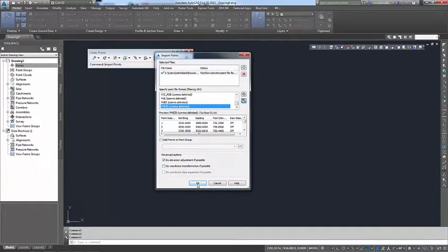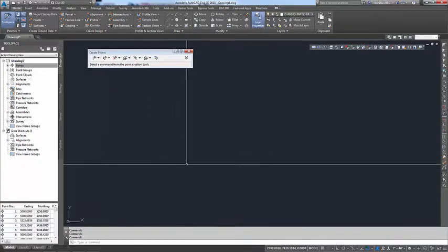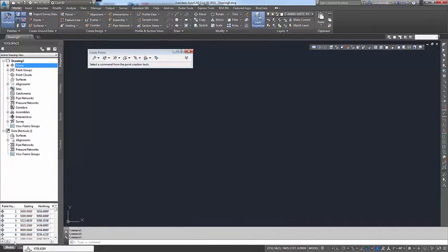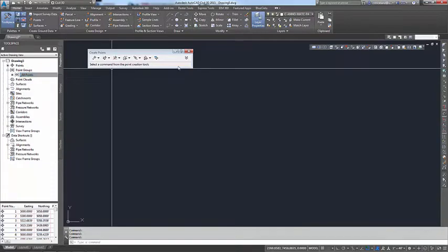It's alright. Hit OK. It brings the file over. In the bottom left hand side, we can see that we now have some points in this drawing here. They match our little preview. We have points highlighted at the top. We have a little square on the left hand side with a dot in it, letting us know that we have one or more points in the drawing, as well as a little plus next to point groups. And the first point group, it too has a little square with a dot, letting us know that there's at least a point or more in it.